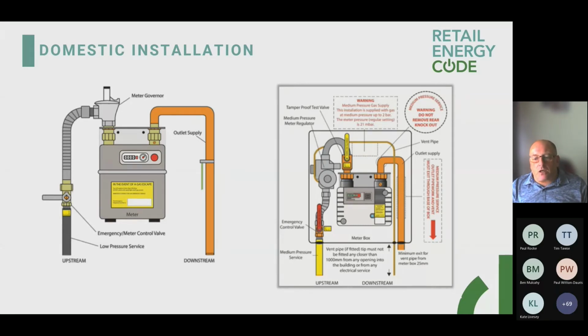As you get closer and closer to where you need it, you step the gas down through compressor stations, and you change the volume of the gas in the pipe, and therefore the pressure at the meter. You may be in a large rural area where it's pointless stepping it down to low pressure because you need the volume of gas to go off somewhere else. So you may take a customer off a medium pressure supply point. But because we haven't decreased it down to the 19 to 21 millibar at that point, it'll be coming in much higher to the